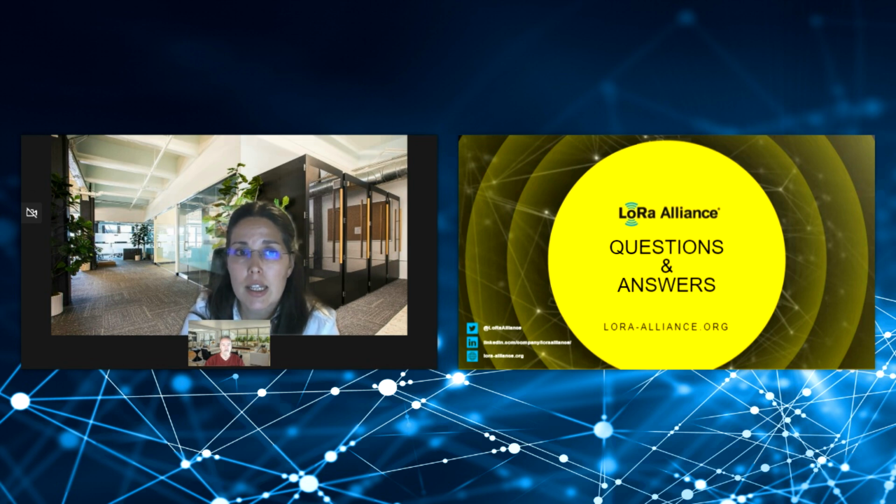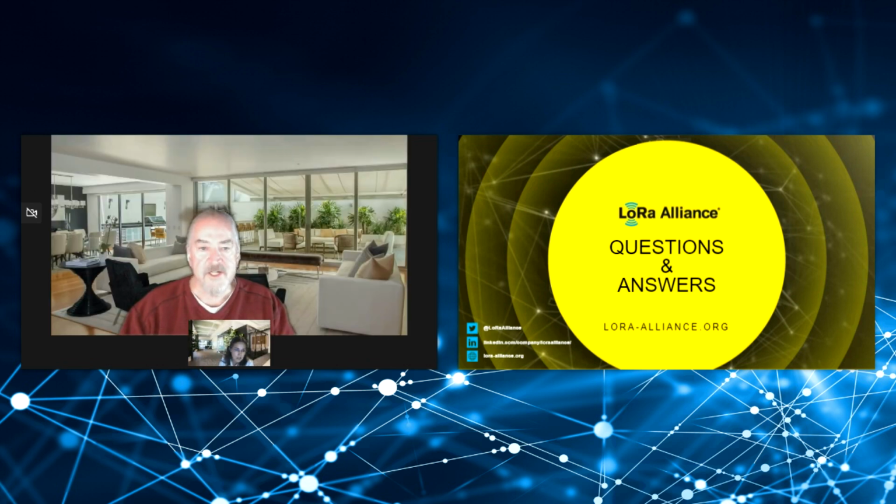In both parts, the end device and the relay, you have to ensure the certification port is enabled, because the LCTT will send testing commands on the certification port 224 to control the relay and the end device during all the tests. Okay, great. Good question. Next one.